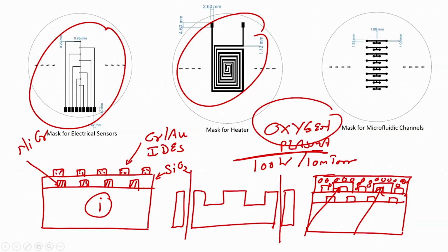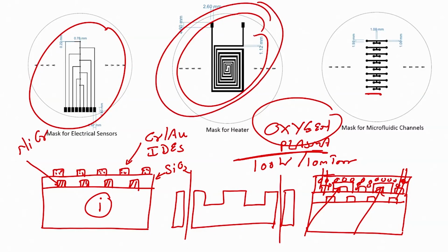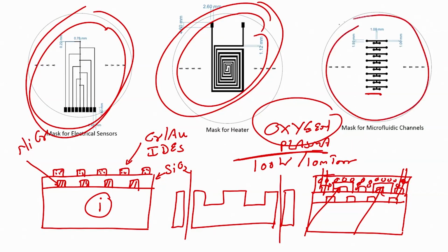By using a punch, by using a biopsy needle you can create a hole in the PDMS. Alright. If you have this, then it is easy to connect the inlet and outlet or to load the drug. So, what we have seen is the process flow for the micro heater. On that there is an insulator, on that there are interdigital electrodes over which there are PDMS channels, and we are sticking all together to get a microchip.